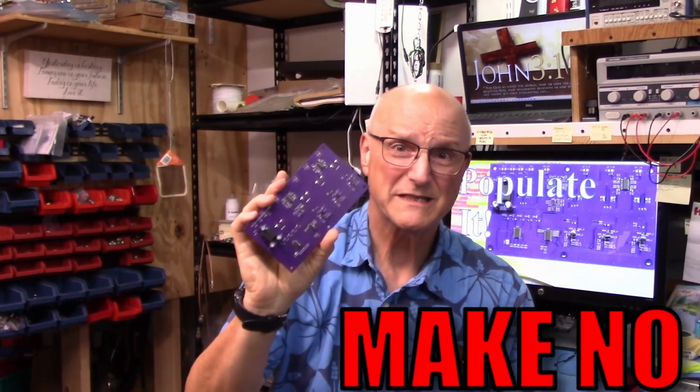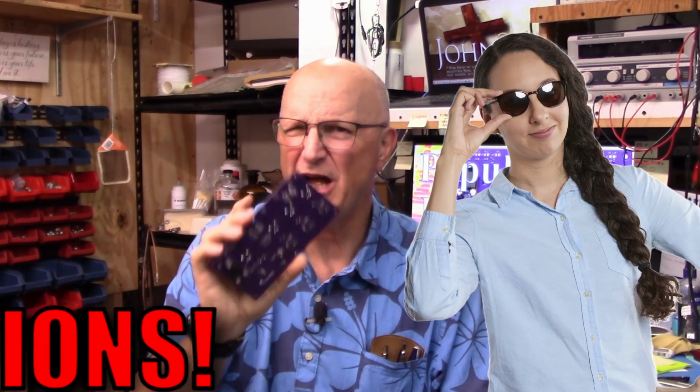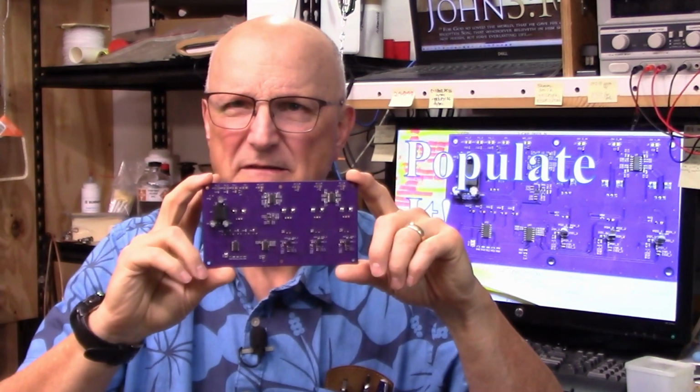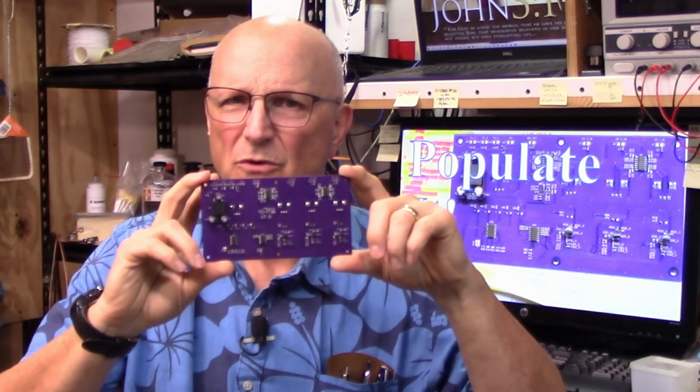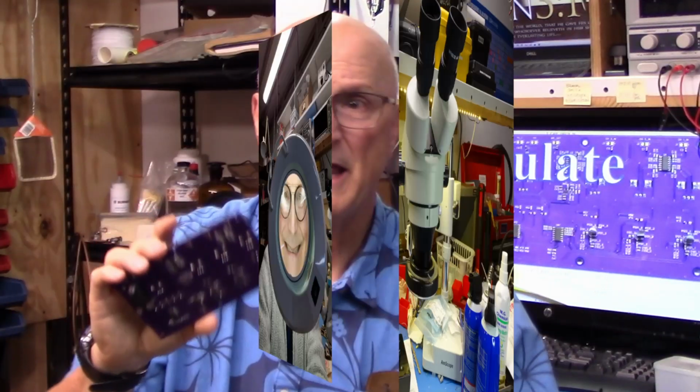Make no assumptions about everything being wonderful. You know you did a good job soldering, but you know what? Stuff happens. And this is where we very carefully inspect every solder joint, every pin, everywhere. We're looking for poor solder joints, solder bridges, anything that might not be quite ideal. Use a magnifying glass or manufacturing microscope for this inspection. And I'll use my AMScope microscope that I use to populate the board to do this inspection.